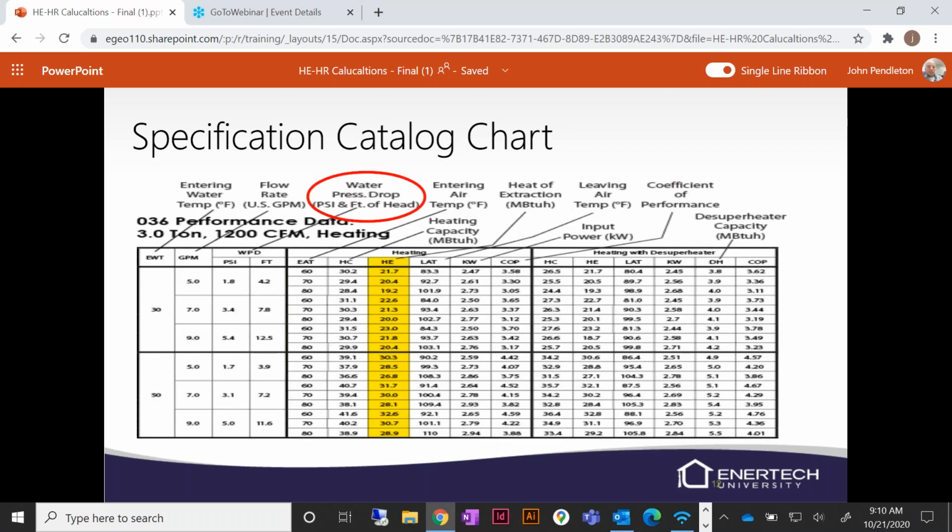So if you take that pressure drop in and out, you can actually figure out, you have to have the manual with your pressure drop to tell you what the GPM is. You can't just say, I don't have a math calculation that says, okay, if I have 4 pounds of pressure drop at 30 degrees, is there an equation that I can figure out the GPM? The answer is no. You basically have to have the manual to tell you with that pressure drop what the GPM is.